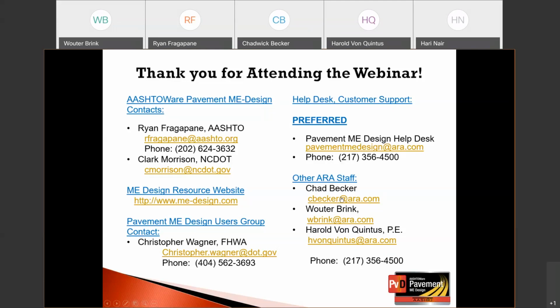You don't have to download the entire database, and Mira is obtained through the LTPP InfoPave climate tool, and NAR is available on the ME Design website where you can download it for your specific agency. You can download all of them if that's what you would like, but Mira is basically on its own. Basically you download a single one at a time.